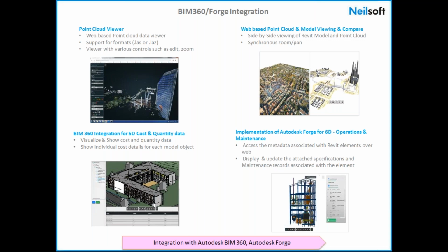Or integration of BIM 360 for your 5D cost and quantity data. So BIM 360 is being used as a collaboration platform, where we can share models, documents and specifications. But for 5D, 6D, there are other systems which are being widely used in the market, and that's where we integrate your 5D system, a third-party system, with BIM 360, so that effectively we can see the model as well as the cost data or the quantity data associated with the model.